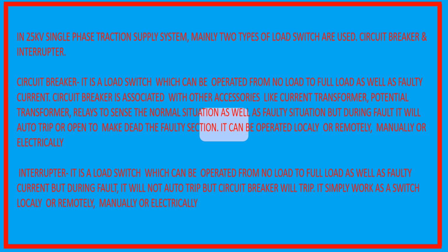Interrupter. It is a load switch which can be operated from no load to full load as well as faulty current, but during a fault it will not auto trip; the circuit breaker will trip. It simply works as a switch locally or remotely, manually or electrically.